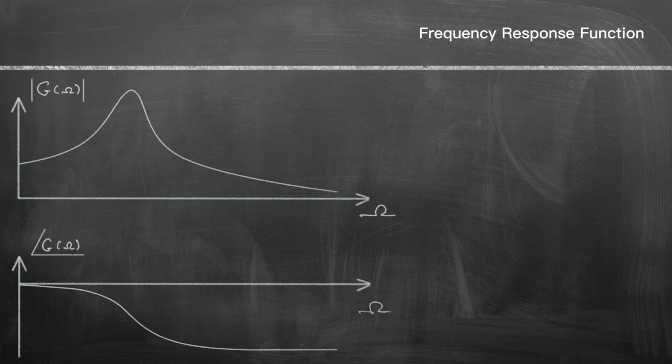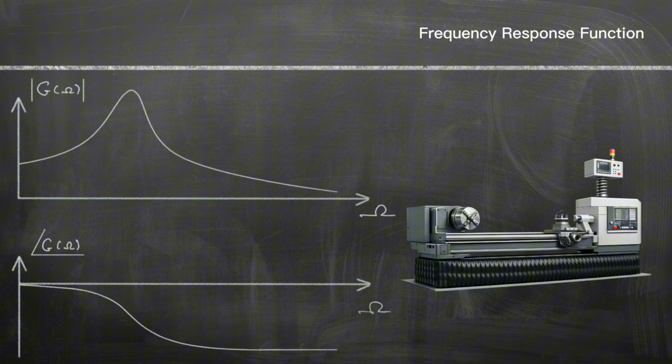In this video, we answer the question of what a frequency response function is, what it tells us about the mechanical structure, and why it is so relevant to practice. Every rotating machine produces an unbalanced force. This cannot be avoided. As an engineer, you are interested in how your system responds to this harmonic force excitation and how the system properties shape the dynamic response at different excitation frequencies.